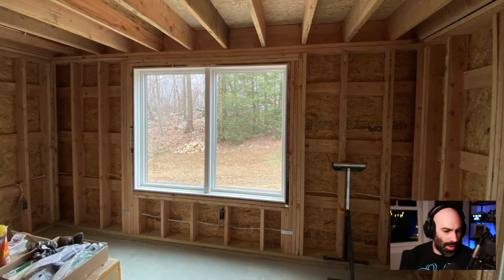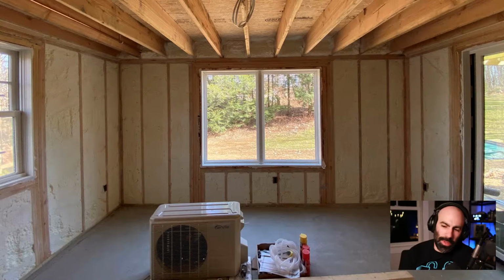And then if we go upstairs to show a little more of the rough. Oh no, here's the insulation. So I did do spray foam insulation. So it was important to make sure that we had the MEP rough, the electrical rough in the walls, and made sure that we had that inspected and approved before the guys came in and sprayed. So again, another tight crunch there, but definitely spray foamed.